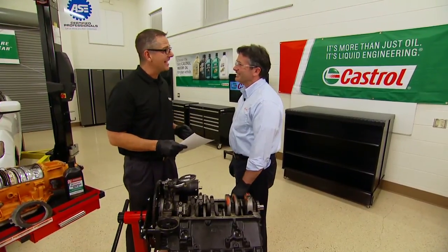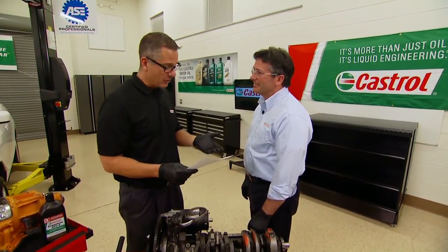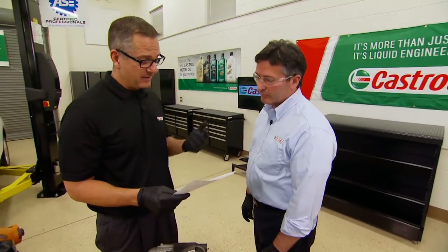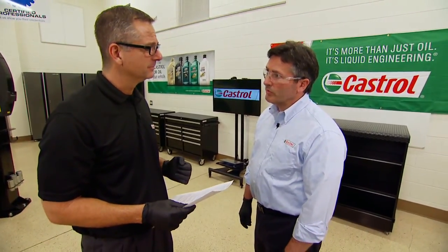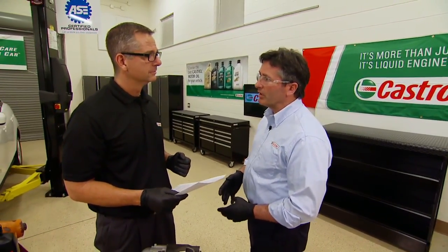Tim, I know there's a lot of additives that go into motor oil. Now I have a whole card here of additives. If I read them off to you, perhaps you can share with us what they do. The first two are detergents and dispersants. John, the role of detergents is to prevent the inside of the engine from getting dirty. The role of the dispersants is to take the potential contaminants that would be in the engine oil and suspend them in the engine oil so that when we drain the oil, we drain the contaminants with the engine oil.